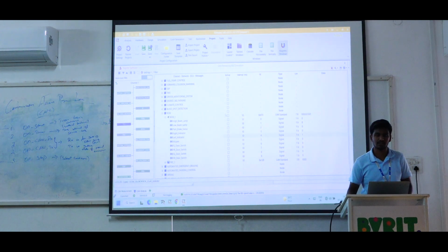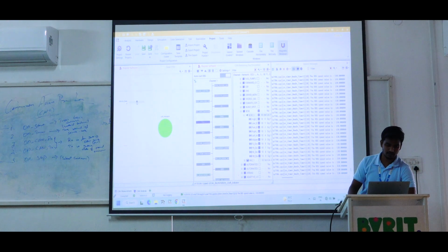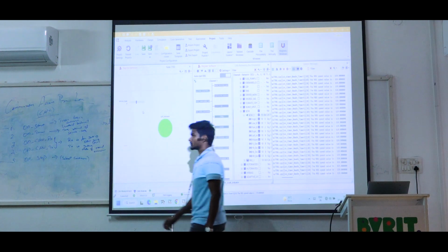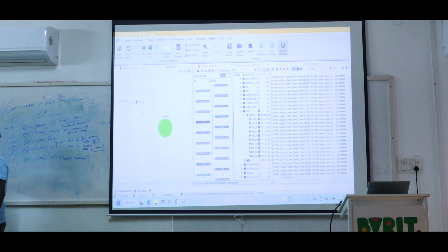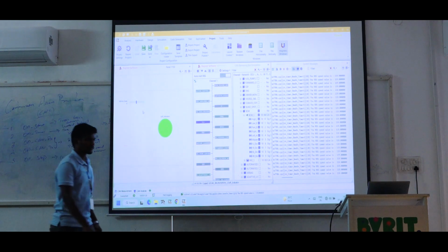Now you have to manually turn on the BCM node and then the BCM message. Manually turning on means the indicator starts blinking automatically. Now you reduce the values to less than 100, it turns off. Greater than 100, it will turn on. Got it?